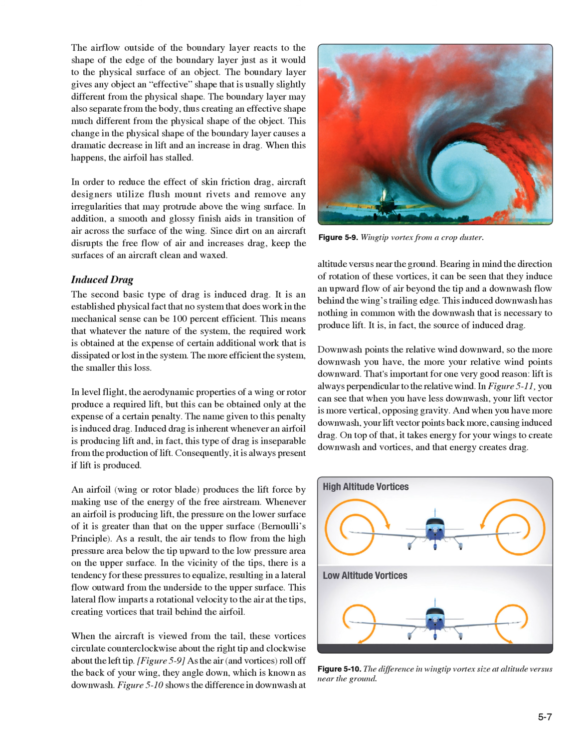An airfoil, wing or rotor blade, produces the lift force by making use of the energy of the free airstream. Whenever an airfoil is producing lift, the pressure on the lower surface of it is greater than that on the upper surface, Bernoulli's principle. As a result, the air tends to flow from the high pressure area below the tip upward to the low pressure area on the upper surface. In the vicinity of the tips, there is a tendency for these pressures to equalize, resulting in a lateral flow outward from the underside to the upper surface.